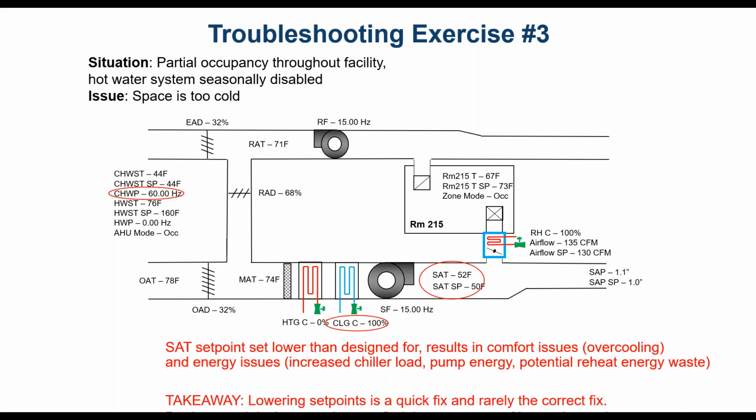Okay, what's the major takeaway here? Lowering set points is a quick fix, and it's rarely the correct fix. Don't exceed design set points. Go and find the root cause of the issues instead.